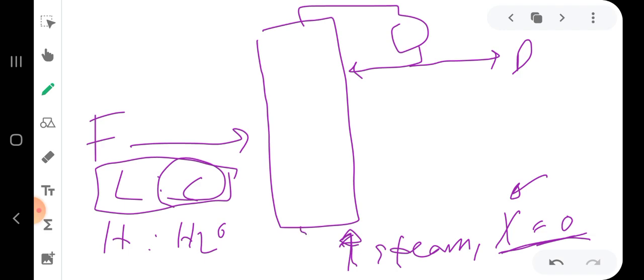And then we're gonna take our product here. This will be the waste with xW, okay? So we don't have a reboiler anymore, and we call it an open system because you see the bottom of the column is an open system. We have inlet and outlet. We don't have a closed loop like the case for the reboiler, okay? That's why it is called the open system steam process, and it's only used when you have the heavy component as water, okay?